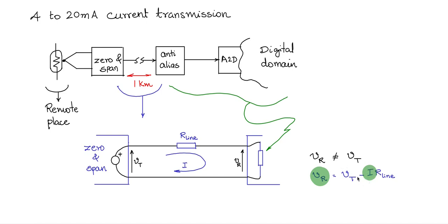But this portion, where it is dependent on I, is the cause of the variability. So Vr, you are not fully sure, because depending upon the load resistance, I will vary, and therefore Vr will vary, and you won't know whether the Vr has varied due to variation in Vt, due to variation in the temperatures, or due to variation in I due to change in load.